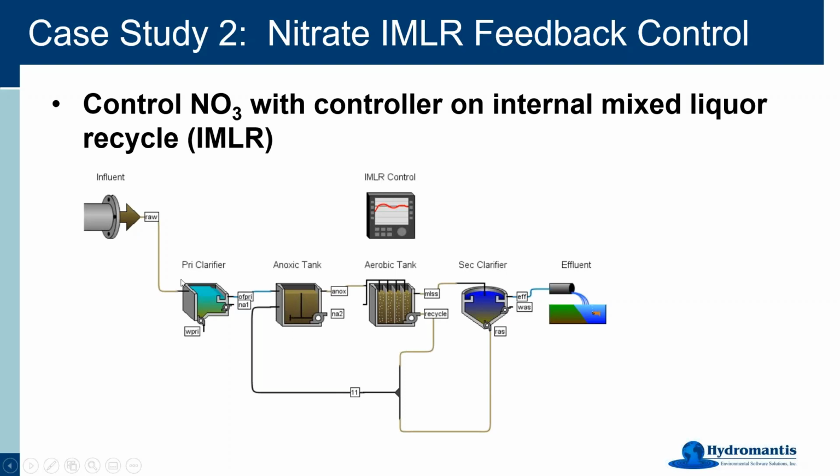We'll take advantage of that sort of quote unquote free carbon that's available in the incoming influent wastewater and use that here. And so if we want to have a situation where we're going to have a predictable amount of nitrate removal, we could adjust this, turn it up when we need it more, turn it down when we don't need it, and therefore hopefully we won't use extra energy that we don't need. Okay, so we're looking at controlling this particular recycle flow, and we're doing that by adjusting and putting a controller on this particular pump.